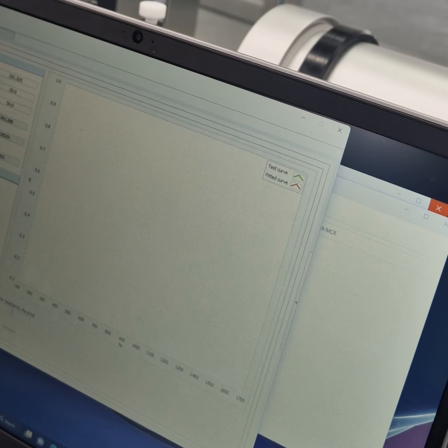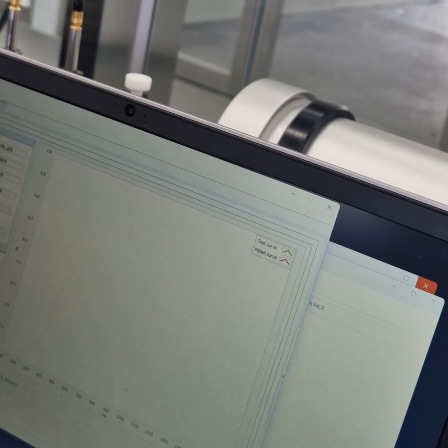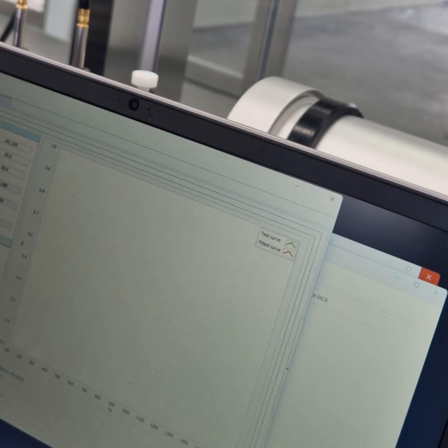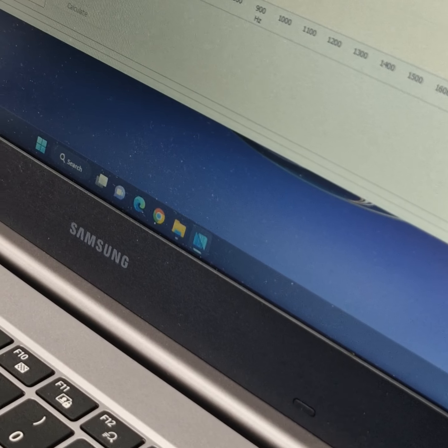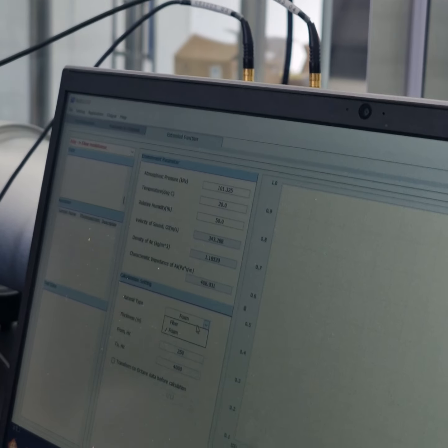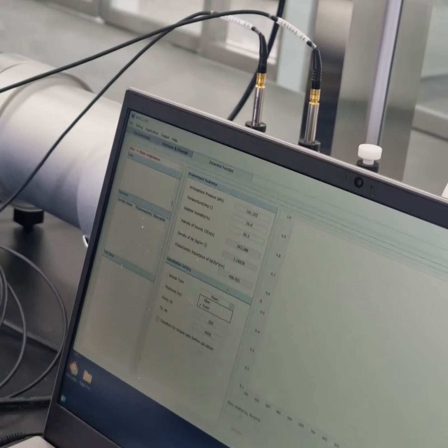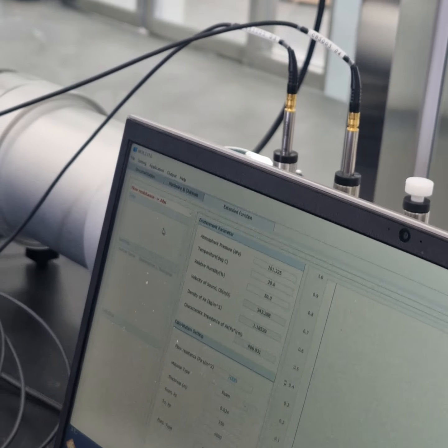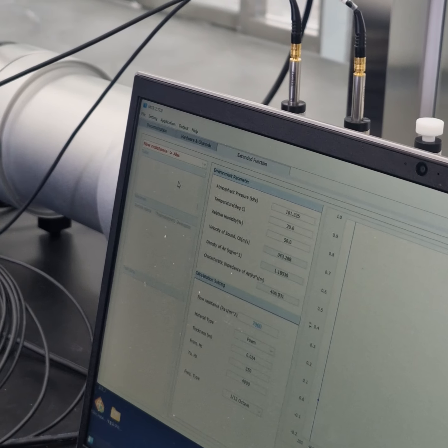If you do an absorption test, then you can see the data here, and set up the property. There's a material type, foam and fibers, two types of material using two different empirical models, and you can predict the flow resistivity of this material, which is pretty accurate. And if we have the flow resistivity of this material, then you can predict the absorption of this material.